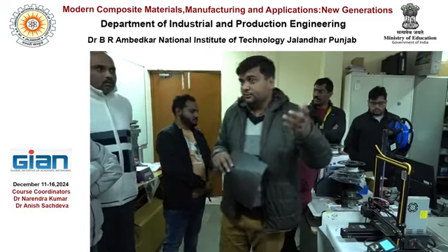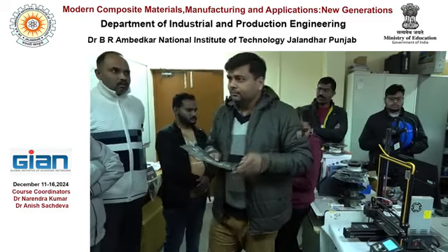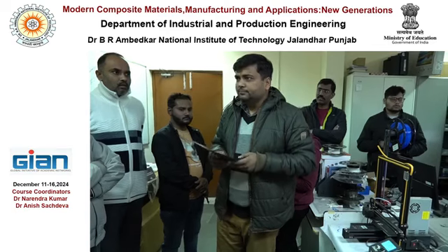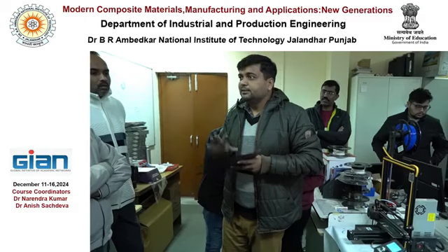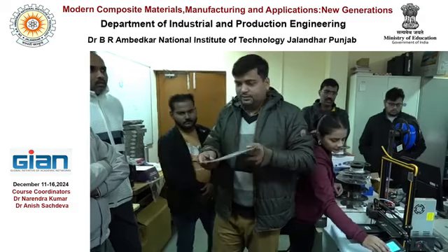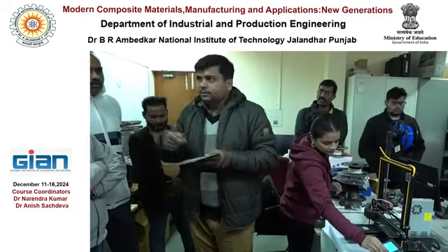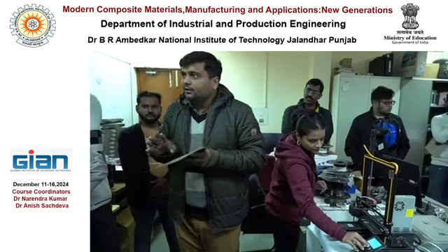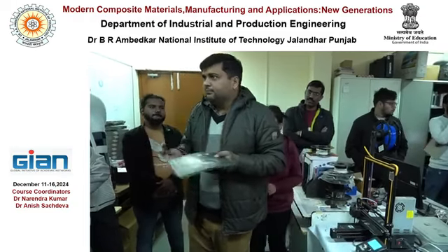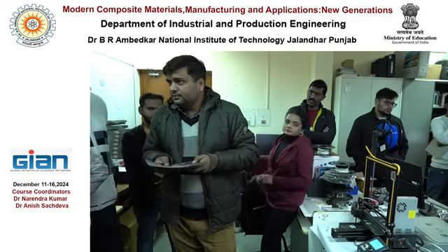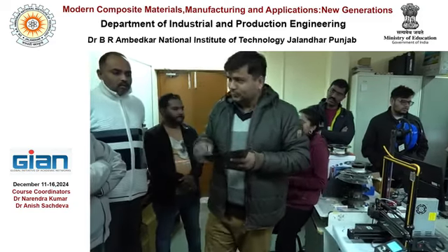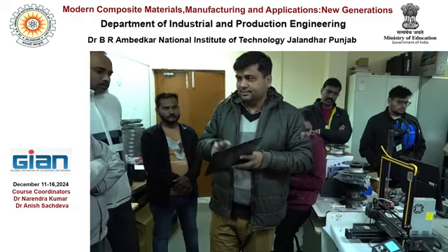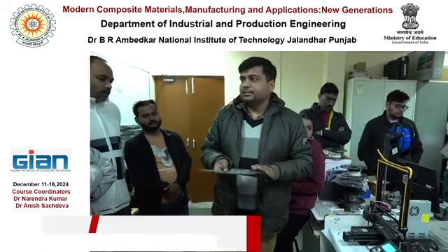But earlier, when I started this 3D printing in 2014, only a fixed bed was available with the 3D printers. So at that time we used to use some tools to remove that sticky layer. Sometimes the parts were damaged, or sometimes part failures also occurred. So that's why nowadays these printers have flexible beds.